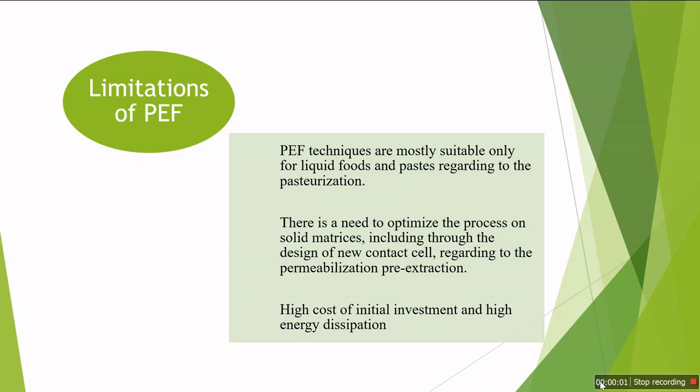And the limitations of PEF. PEF techniques are mostly suitable only for liquid foods and pastes regarding the pasteurization. There is a need to optimize the process on solid matrices, including through the design of new concepts regarding the permeabilization pre-extraction, high cost of initial investment, and high energy dissipation.